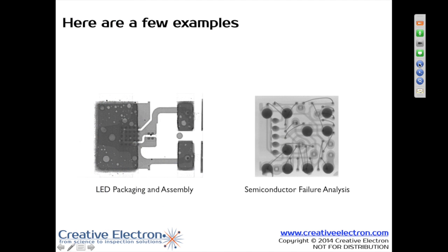Okay. Typical applications with X-ray, LED packaging. That's become a large market for us based on the fact that luminaries create quite a bit of heat, and the heat distribution is really key in the lack of voiding, essentially how well you have it glued to the board. And we've done really well at being able to pick out that voiding.